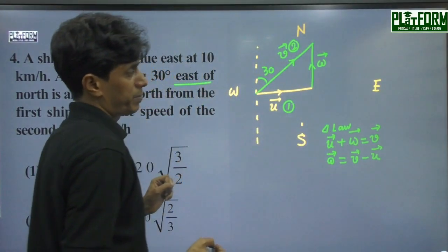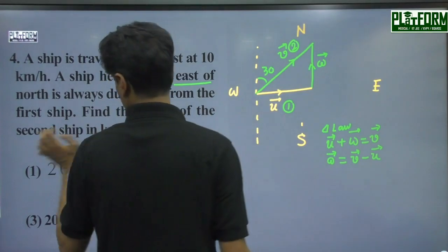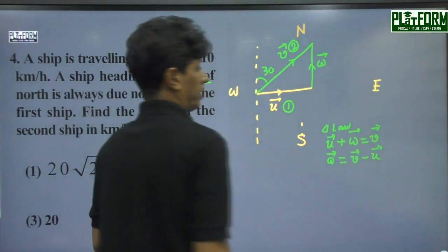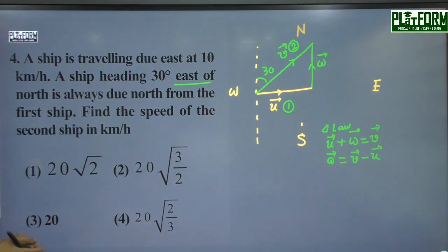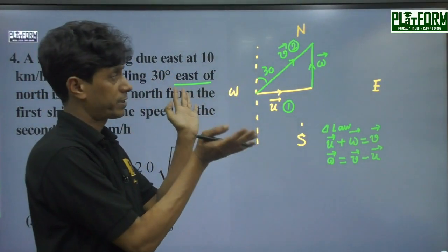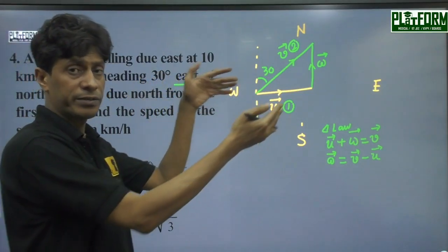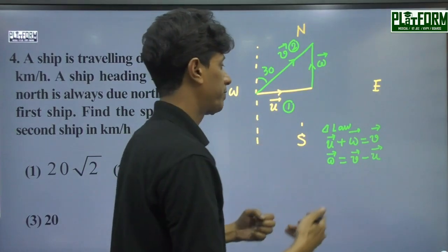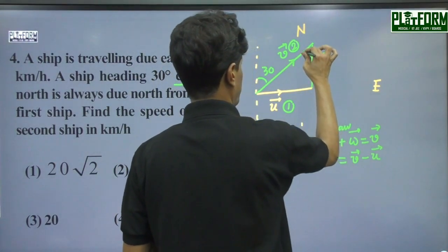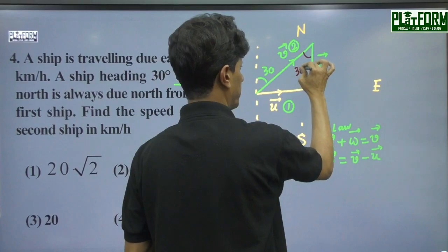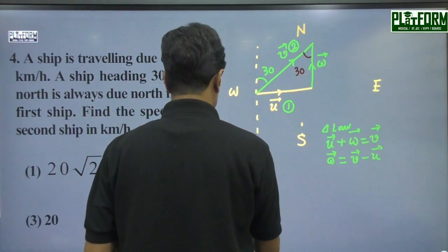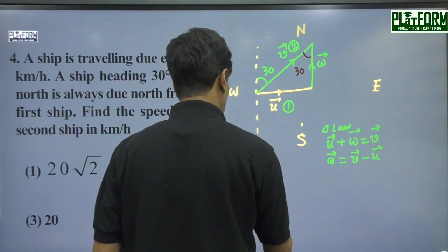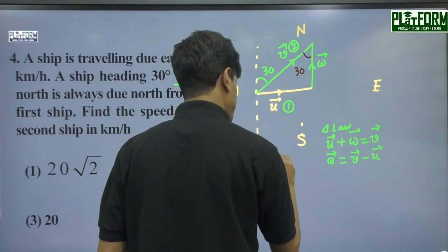So the problem is very simple. If we draw the triangle by taking the two velocities as adjacent sides of a triangle in reverse order, with the third side's arrowhead towards 2 representing the relative velocity, and from this the angle is 30 degree, we have to find v by u equal to cosec 30.